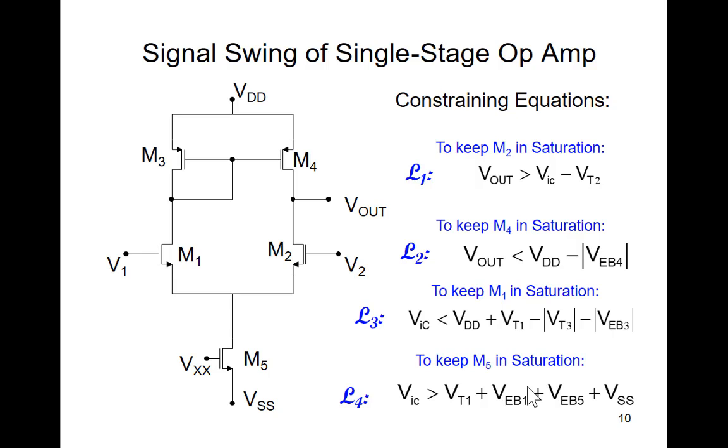Let's play the same game with this structure. Is this a reference op amp? Not quite. It's almost, but what's different here? Diode connection. So the reference op amp only has a single-input output. This one, but you could have taken the other output on the reference op amp. This one has a diode connection, so it has a factor of 2 increase in gain and a factor of 2 increase in gain bandwidth product and slew rate relative to the reference op amp.